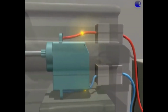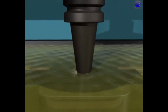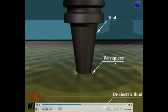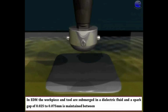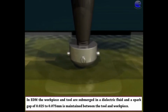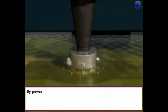Whenever the power is on, the power supply is given to this EDM process and it starts working. What is the principle of this EDM process? There are the major components. This one is the tool, this one is the workpiece, and it is immersed in the dielectric fluid. In EDM, the workpiece and tool are submerged in a dielectric fluid, and a spark gap of 0.025 to 0.075 mm is maintained between the tool and workpiece. That is a very important parameter while carrying out the EDM process.